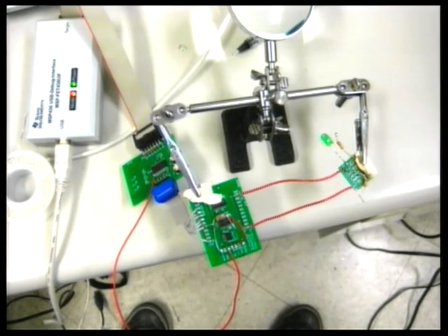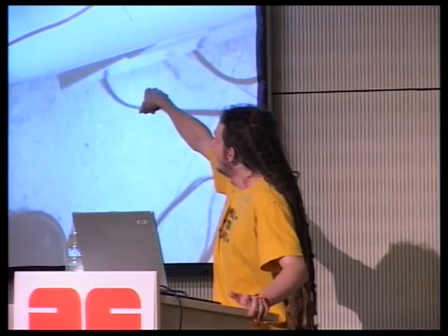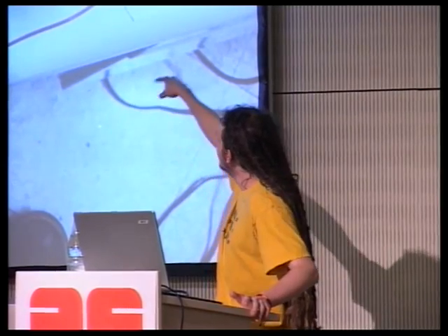But in this layout I had a modified BSL cracker, and then I've got a voltage glitcher, and I've got my business card. By triggering the glitch, I can make the business card skip into the section of its code that starts blinking that LED. Now, it's not terribly useful if all you can do is light an LED, but